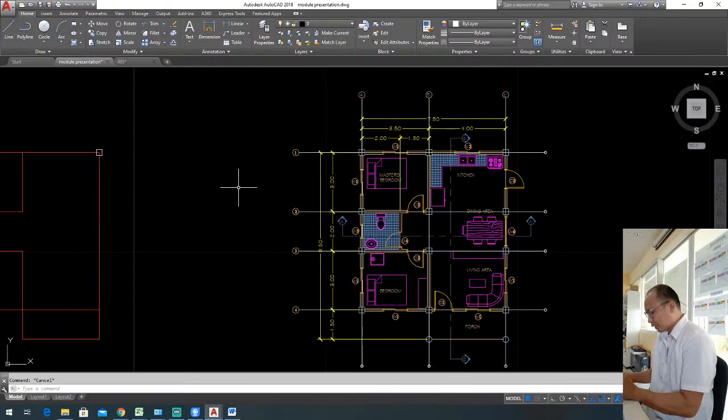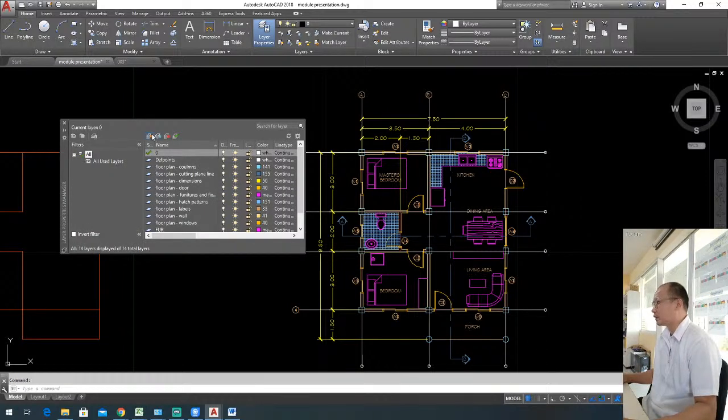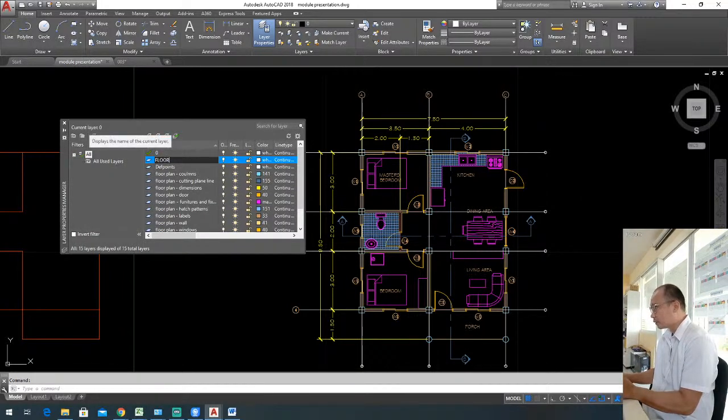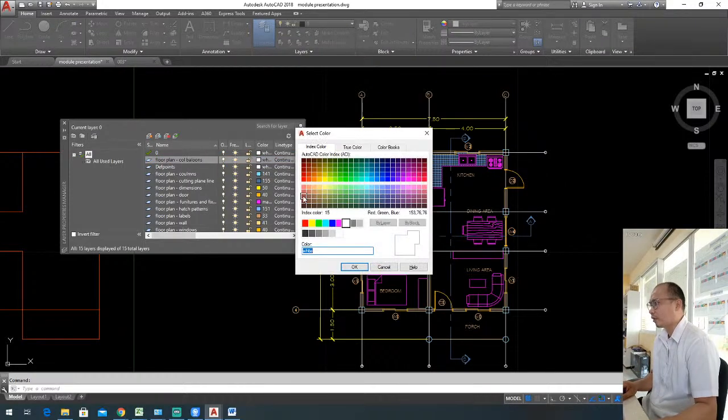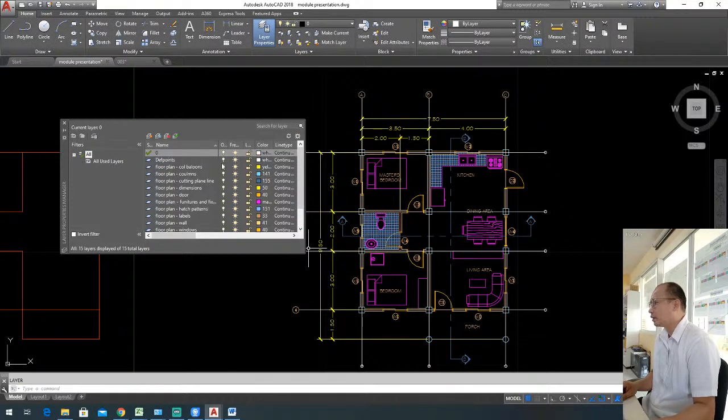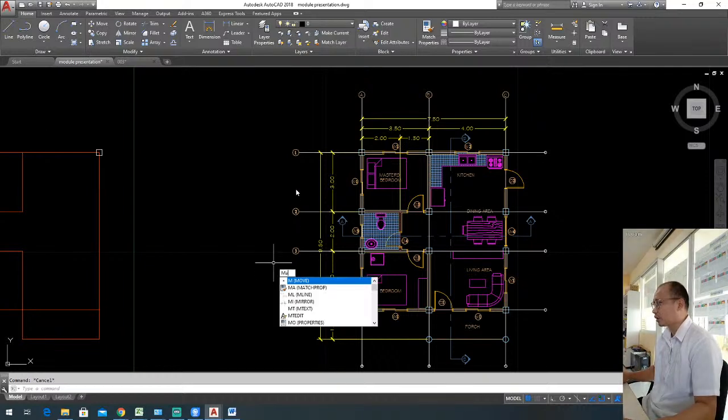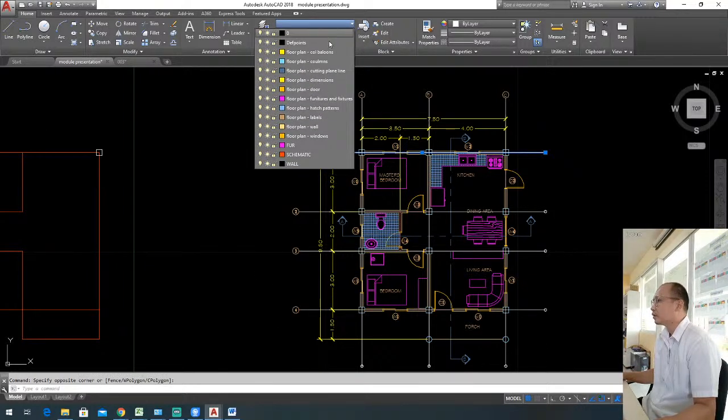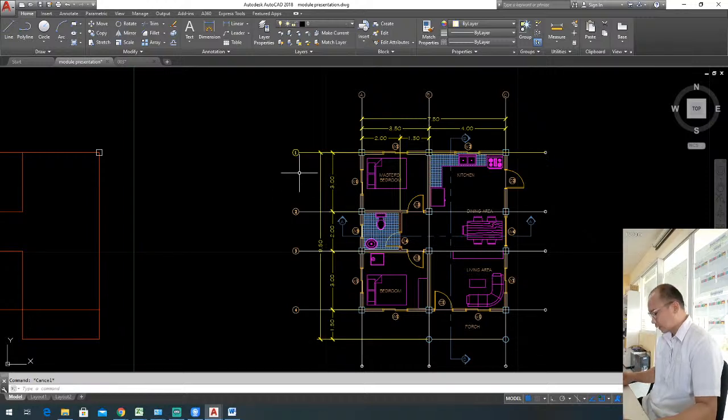And after that one, I'm going to layer that one on my floor dash column balloons. Okay, and then go on colors. I wanted to have the same color as all of the dimensions, and the line weight would be the same as that of the dimensions. And then I'm just going to click that one, then column balloons, and then go on MA. Alright.